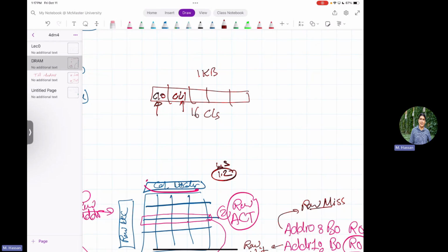True. This is why we say a lot of scheduling happens in the memory controller to be able to put requests that are targeting the same row back to back. But not only this, it also depends, before the scheduling, on the application pattern itself. Because if your application has a very large stride that jumps 2 kilobytes, like a row-wise matrix multiplication, for example, then you will jump even larger than the row buffer granularity. So you start having row conflicts. So like everything that is managing performance in our discussion, it's application pattern dependent and hardware capability dependent.